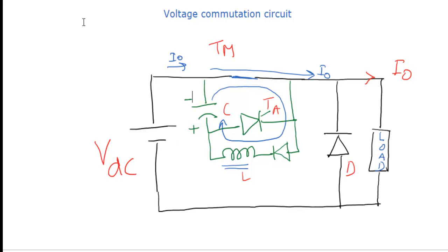Okay, so now the inductor keeps on charging the capacitor. That means all the energy will be transferred back to the capacitor. Once all the energy is transferred back to the capacitor, the capacitor voltage becomes VDC again. Whatever energy was transferred to the inductor, it got back. So voltage becomes VDC. In this case, the inductor is completely discharged, so there is no current in the circuit.